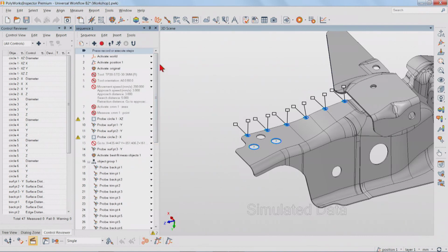Although this could work immediately as is, you're going to notice this warning here that tells you that because I used surface comparison points and circles when I started this best fit measurement object alignment, now that the CMM pre-alignment is gone, in order to be able to measure those features, I could choose to disable the guided mode by not restricting the points to be acquired to those points. Or you could also add a pre-alignment that is very common to any portable devices.